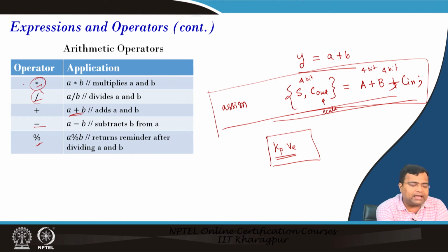When you write a multiplier, if it is implemented in FPGA, the FPGA will have some IP core which has a dedicated multiplier cell, and it will assign that multiplication operation to that cell. But if you want to go for ASIC, then this multiplication has to be translated into some logic. What multiplier logic? Multiplication can be divided into sequential addition plus shifting operation, or it can be a direct multiplier, which can take many clock cycles.